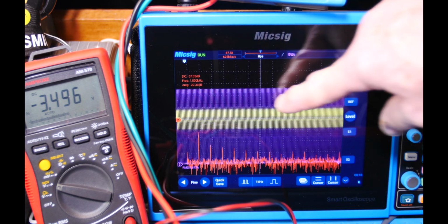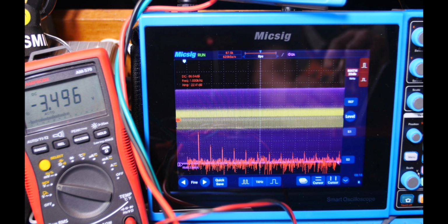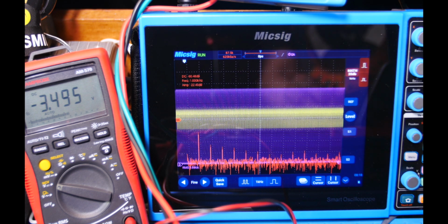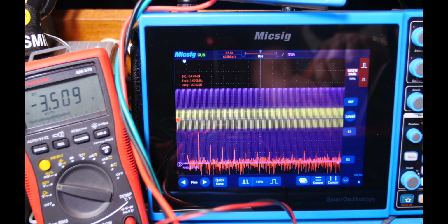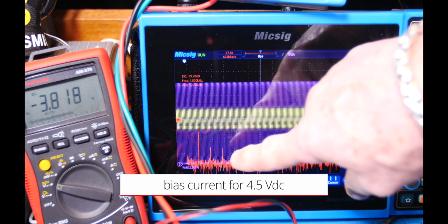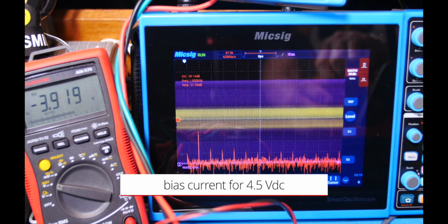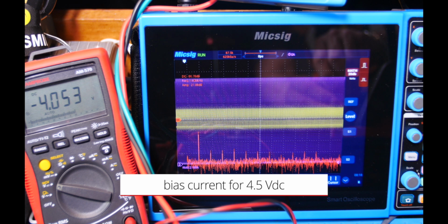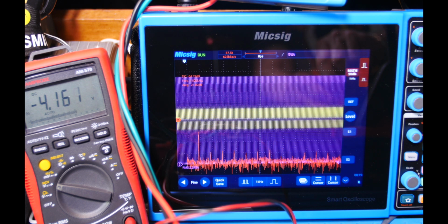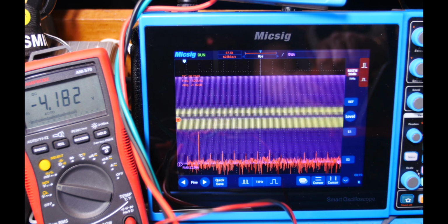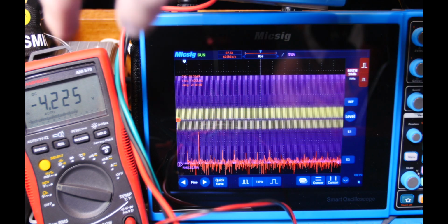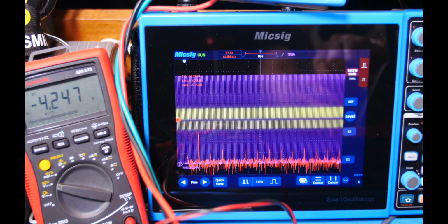I have to get enough cycles to get a good FFT. That's why we got so many cycles up here. But now what I do is, watch this. I'm adjusting the current on the output and see how that distortion is just dropping. So before I didn't see that because I had my signal too high and I think the power supply was clipping out. Look at that, I can get it to drop right down. So we're supposed to have this about 4.5 volts and look at that, it's starting to drop right away.